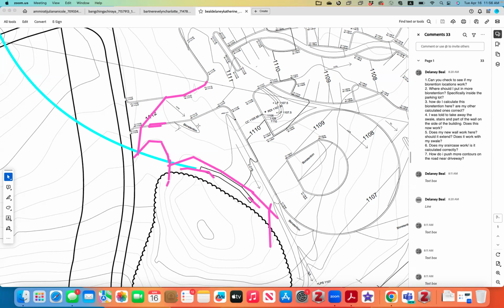I am not sure. I think you might have a little bit of 1102 coming out of the curve here. You need to double check. Now, looking at the distance here, this looks like 1102 on the landscape. You offset by 25 here because this is a parking lot contour and that is a landscape contour. The spacing should be 25.